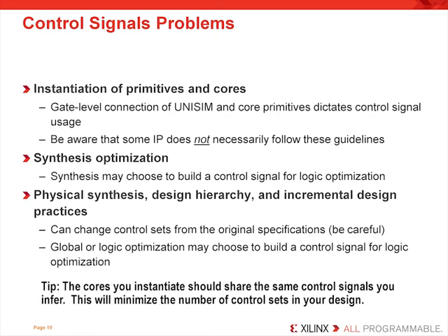Likewise, if your design is large, plan on evaluating your synthesis results as early in the design flow as possible. This may be necessary since your synthesis tool can also choose how to build a control signal based on how it optimizes your design. This includes the use of physical synthesis tools such as Amplify, global optimization settings, and logic optimization settings. So always take the time to verify your synthesis tool generated the anticipated and appropriate control signals that you expected.